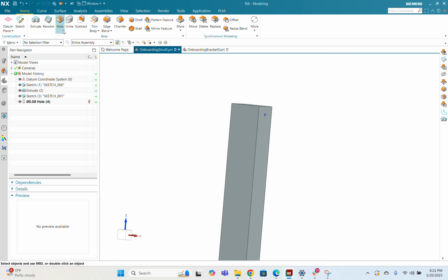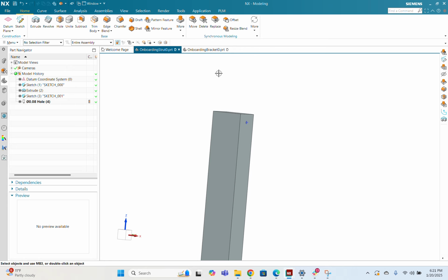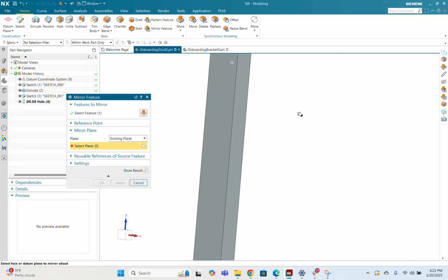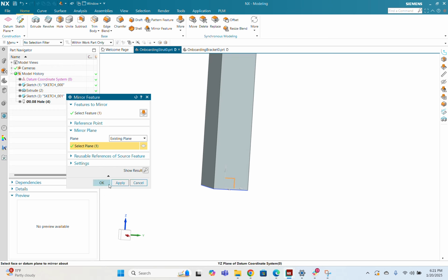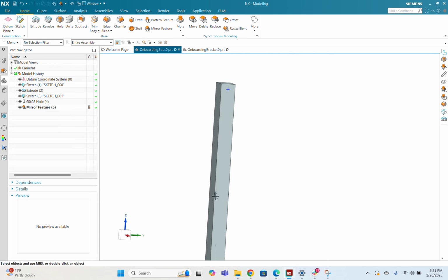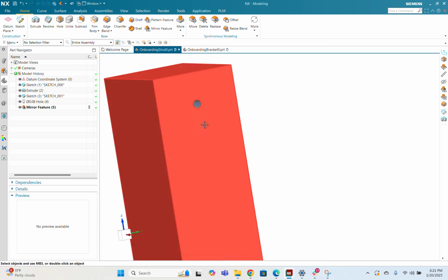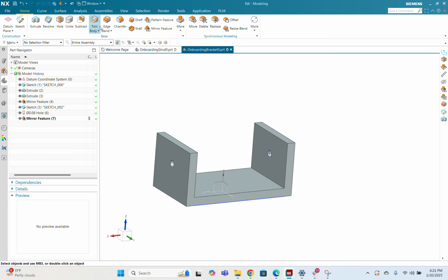Now you can see that only drilled a certain depth in. And then similarly to how we mirrored the hole on the bracket, you can also mirror this over to the other side. I'm not going to do it for time's sake, but that's how you would do it, is you can just mirror again across the YZ plane. Here, I can do it really quick. And then you'll see it'll just mirror your hole over to the other side.